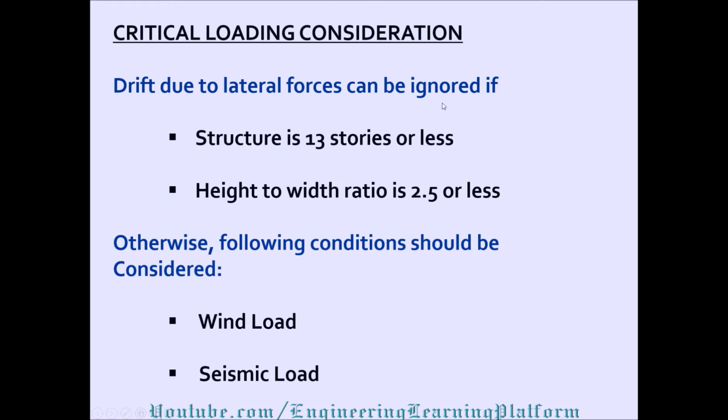Critical loading consideration. Drift due to lateral forces can be ignored if the structure is 13 stories or less and the height to width ratio is 2.5 or less. Otherwise, the following conditions should be considered. This is not recommended in any code, but this is what I am telling from experience working in a design office.